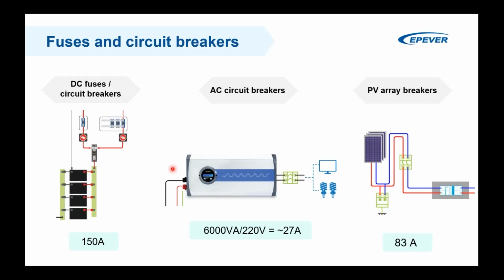It can be a single pole or double pole. Normally we use double pole for AC. We also discussed the current rating and the speed of blowing. It should be a fast blowing breaker here and on the input side as well.